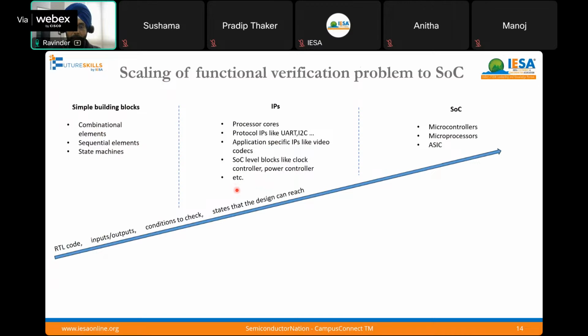What we normally follow for a small IC is okay. You can handle it. You can have an SoC level test bench and verify it. But for a bigger SoC, which we discussed, which has scores of IPs and processors, a complex SoC, what we take is a hierarchical verification approach. What is the hierarchical verification approach?